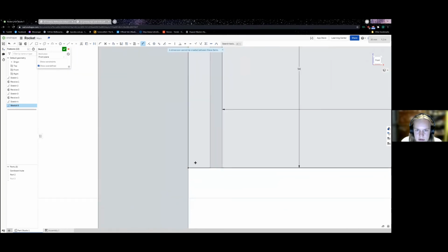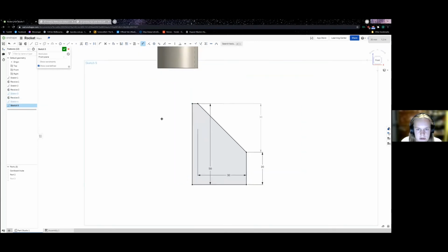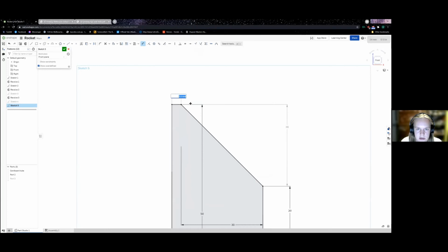no, it doesn't want to do that. Okay, I'll just hide that sketch real quick. Okay, if we dimension between here and here, it's giving us 3.4 millimeters currently. So I'm just going to knock 0.4 mil off that. That'll give me plenty of room.